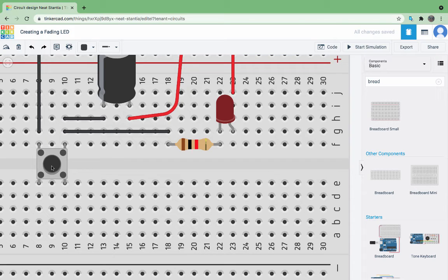When I'm pushing this button, I'm also sending electrons into my capacitor, so it's getting a charge. But when I cease to be holding this push button, this would still be connected, so they can flow out of here and then to my LED until I run out of the supply that's in the capacitor.